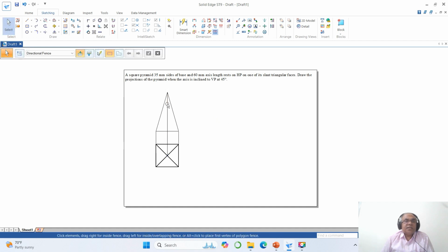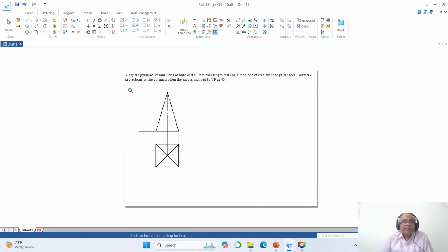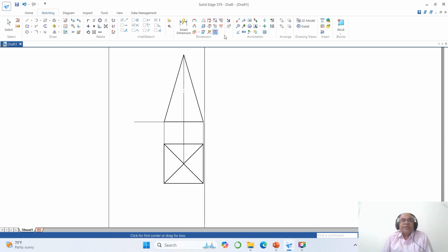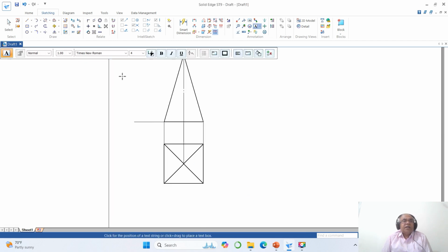Then you select this line and make this the axis line, and then you select these three lines and make it 0.5, and then you make that a group. Select this line and group it. Now once you do that, you come down to Zoom Window. Sorry, you just go to Line and draw one horizontal line of any length. Now you come down to Zoom Window, bring it near to the screen and go to Text.